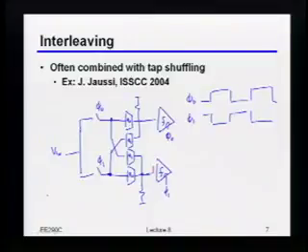As we'll actually talk about a little bit more later on, it does depend a bit upon what you're doing afterwards here. So if I'm really just making decisions, then probably it makes sense to do this, because all of the latency and bandwidth of everything after the sampling point is relaxed, right? It's relaxed by about a factor of 2. Whereas if I reserialize it, then again I have to deal with the full bandwidth, right? But if, for example, I'm actually trying to build a DFE after here, it's not so clear that having the relaxed bandwidth helps, because as we'll talk about in 1 second, the DFE itself will introduce a bandwidth constraint.